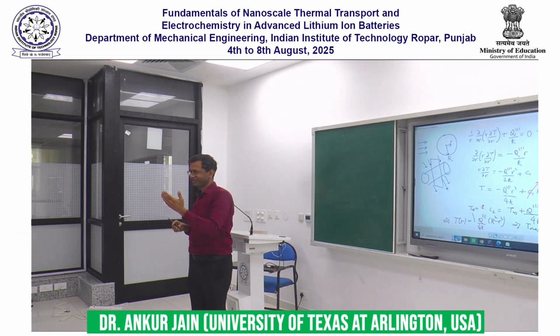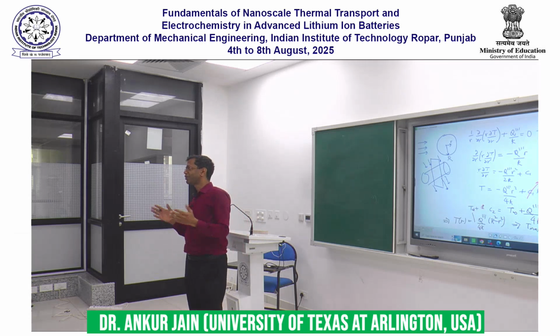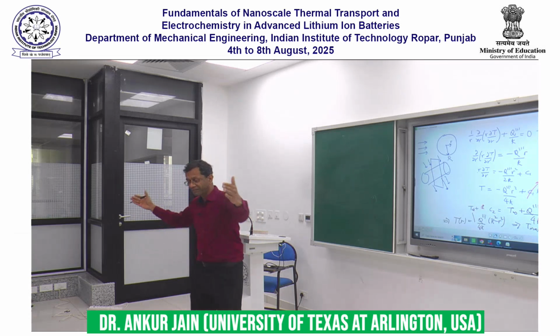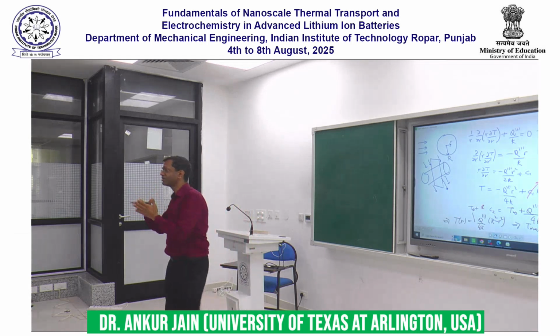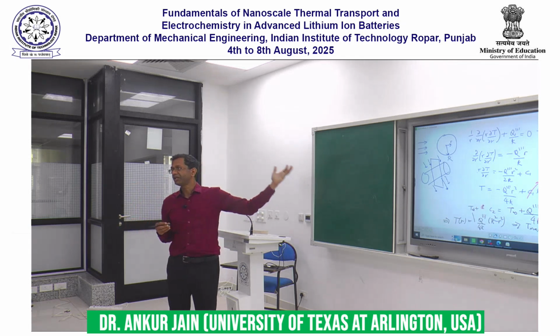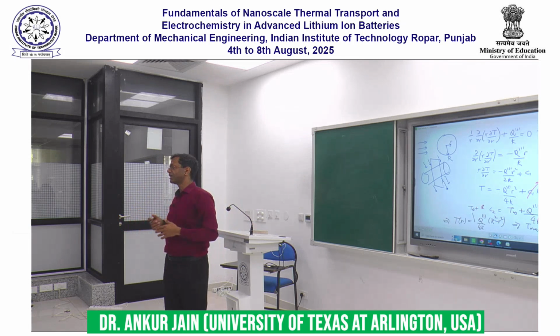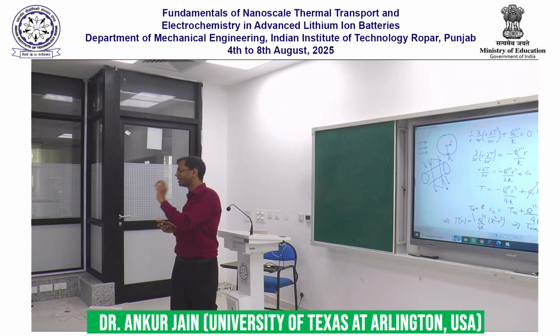Surface area is, yes, exactly. The surface area is what is creating this trade-off here. Instead of having one very big cell, I really want to have a large number of individually small cells. That is the reason why typically electric cars and most other applications for batteries still use relatively small sized cells.